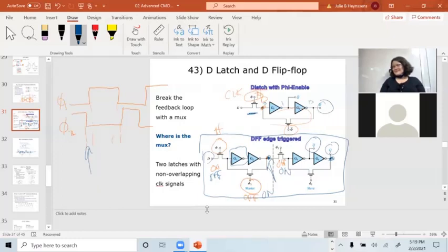Yeah, because the way we designed our gates, every inverter, every AND gate had to be able to drive 10 loads. If I had to drive 12 loads with something, I would take that one output and run it through 2 inverters, and run it through a second set of 2 inverters, and drive half of them off of one and half of them off the other.